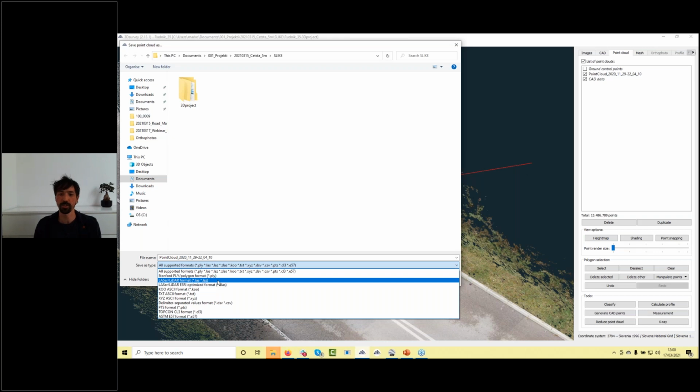If you have a total station or laser scanner, you can easily import them in 3D Survey. If you're using laser scanners from Leica or something like that, I suggest the laser file format. The E57 usually cuts the coordinates off because they are too long, and then you don't have the data in the right position. But if you save the coordinates as a laser file and import the point cloud like that, everything works perfectly.